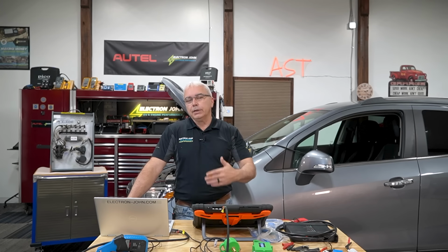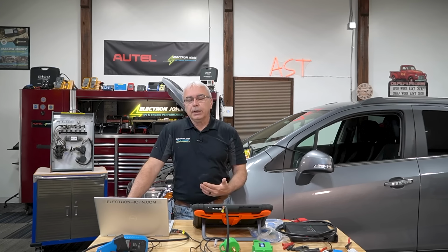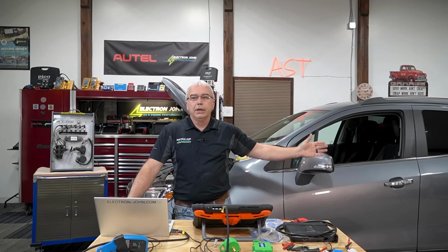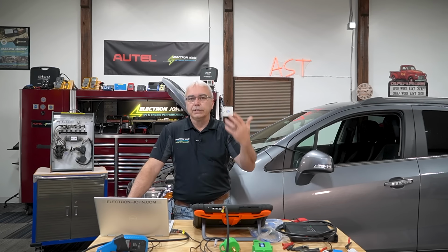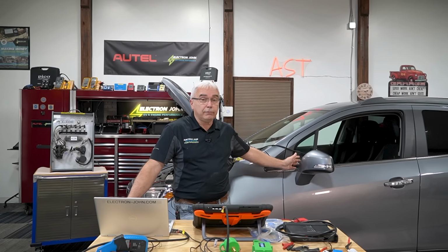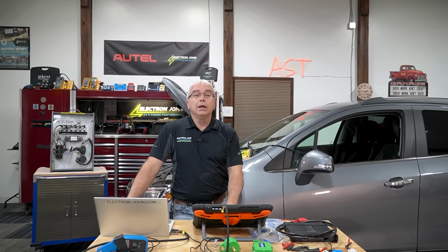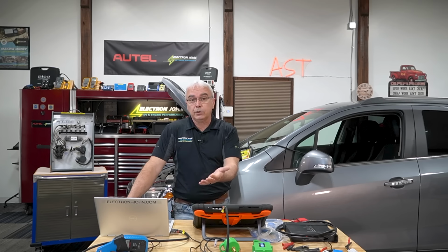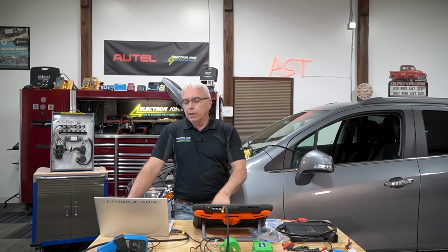It's not just going to be weak or restricted at idle or off idle. It's going to have a lack of fuel pressure the entire dynamic range. So this is how I can start using some of this stuff so that when I get out of the driver's seat and start doing pinpoint testing, I know the series of tests that I want to do. Again, it may change once I open the hood and see how hard it is to do.